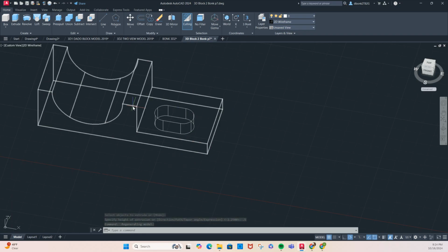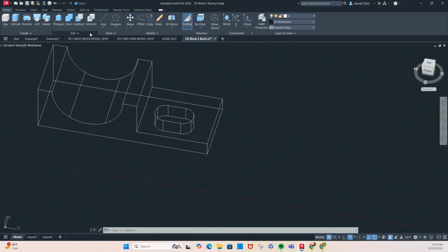Modifications. So you got to do a 1/4 inch fillet in here and a different kind of fillet on the outside here. So watch this. You're going to do edit. These are 3D fillets. I'm going to click where it says radius, type the measurement in, 1/4. All these tools have sub menus. So I'm using the radius command. I just typed in the measurement. I'm going to click this inside corner and then hit enter. And that built that 1/4 inch radius there. You hit enter again, it says to accept that, right?